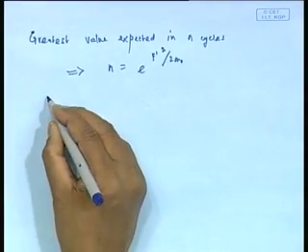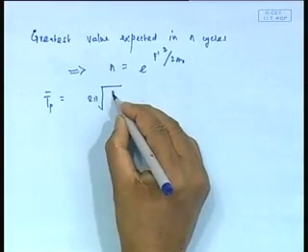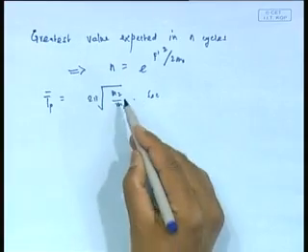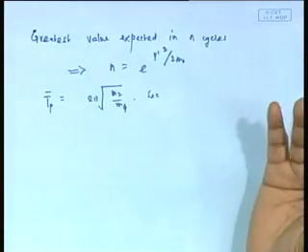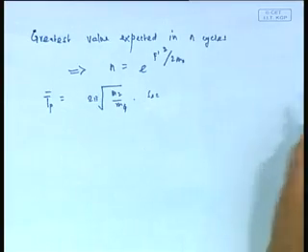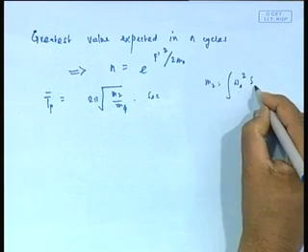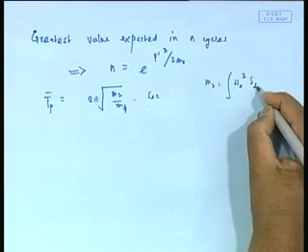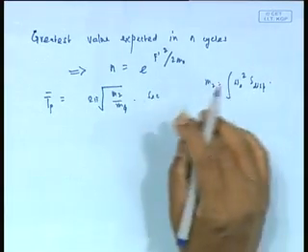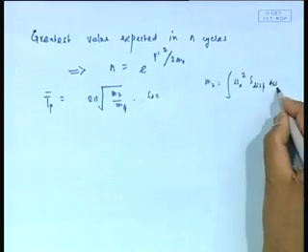See, we can find out the typical peak period of this spectrum, given by 2 pi square root of m2 by m4 seconds. M2 and M4 are basically, as you know, the area under the velocity and acceleration spectrum, or you can say integration of omega e square times the displacement spectrum for m2, and m4 is omega e power of 4. Here we are talking of relative displacement, relative velocity and relative acceleration spectra, d omega e, you can see.